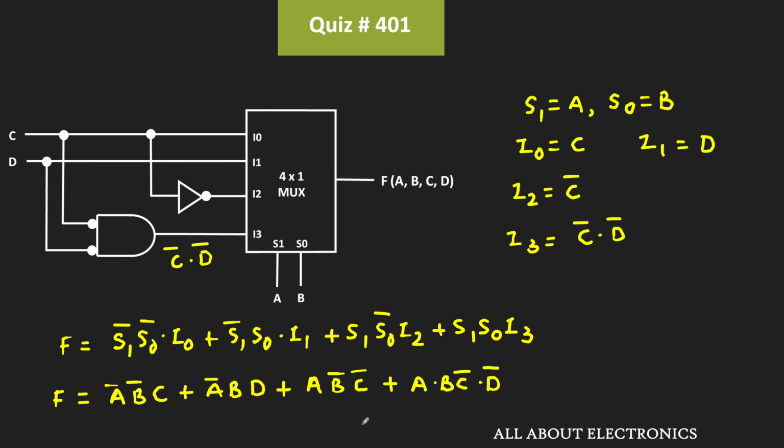So now let us expand this expression and find this logical expression in terms of the canonical SOP form. We have already seen how to expand this non-canonical SOP form expression into the canonical form. But the easiest way is to map this function in the K-map. And from the K-map we can easily identify which minterms are present in this function. So first, let us map this function in the K-map.